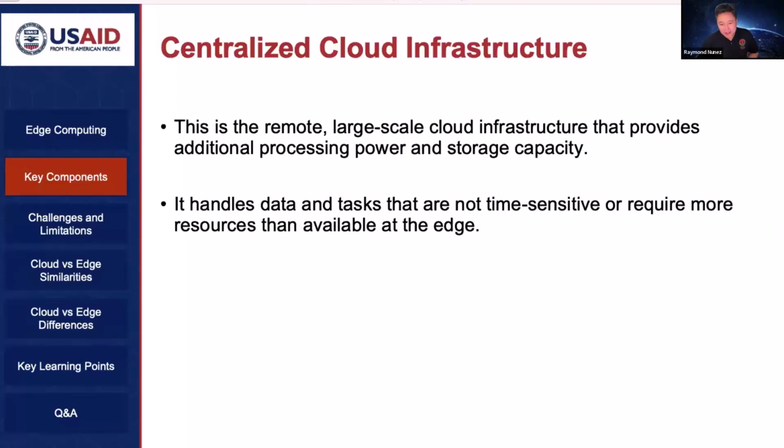So you might be googling it and say, oh, it's only 5 Mbps naman. Yeah, let's just do simple math. 5 Mbps per camera, 50 Mbps in total. Shifting all of those data to a cloud solution, maybe a wireless cloud solution, you might not have 50 Mbps on the bus's route. Some might have good connectivity, some might encounter spotty connectivity. And that's just one bus.